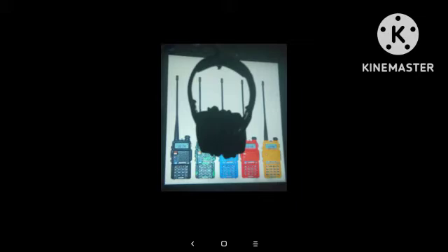40. Resonance is the condition that exists when inductive reactance and capacitive reactance are equal and opposite in sign. 41. In a parallel resonance circuit at resonance, the circuit has high impedance. 42. What property allows a coil wound on a ferrite core to mitigate or reduce the effects of an offending radio signal?